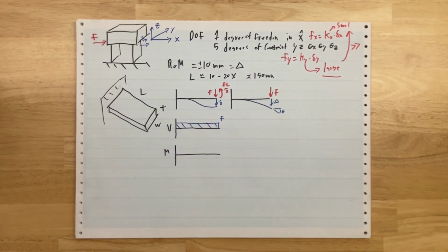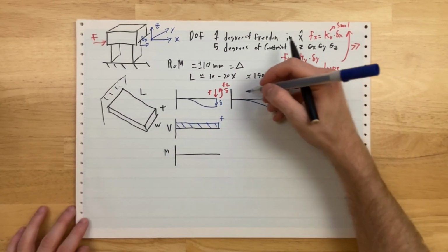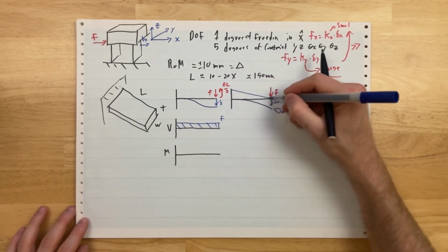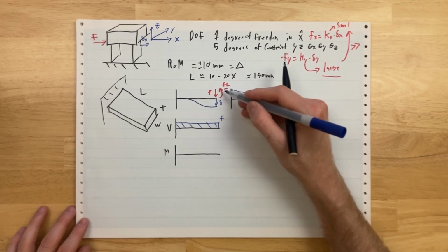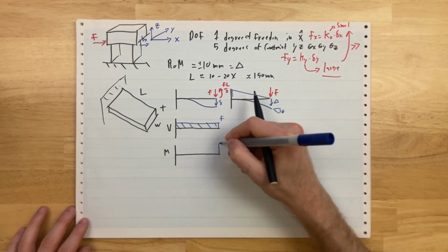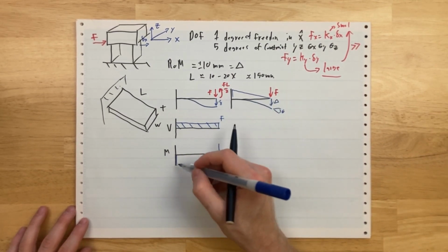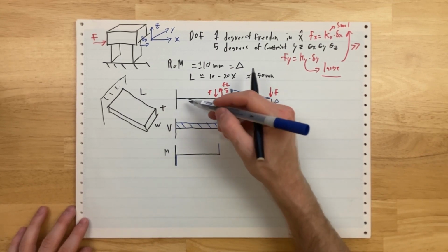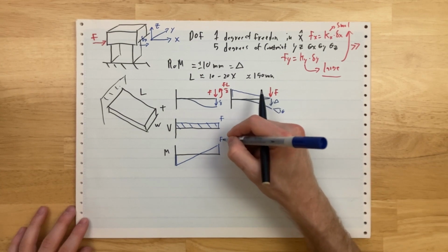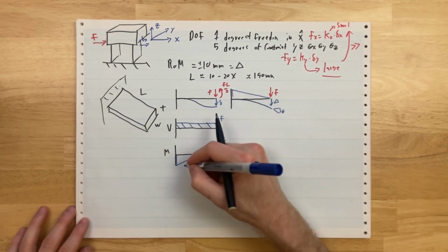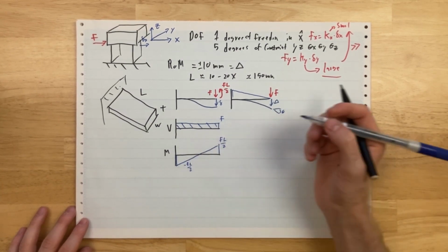Essentially, in the cantilevered beam world, you have a peak moment at the root, decreasing towards the tip. You're slowly just gaining moment over time. We actually have an applied torque at the tip, so we have to immediately jump up to the full moment, and then by symmetry, it should be the same on the other side. This shape is obviously symmetrical, and you end up with a peak moment of FL over 2 and minus FL over 2.